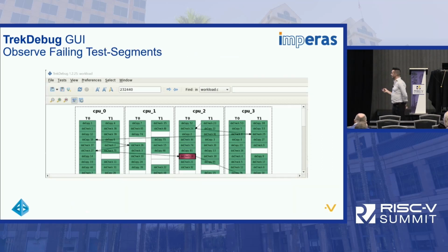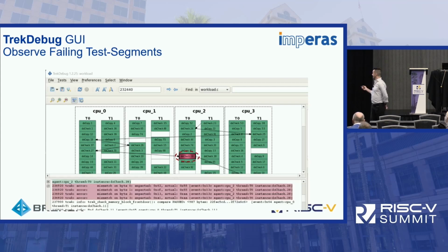What you actually have the capability of doing is taking a scenario and then see how that scenario is executed and where the context switches are, where you switch between different processors, between different cores from the beginning to end. And we think this is a very powerful tool, especially when you're getting errors, because you can see not just where the error happened, but you can also see what else was going on in the other cores and the other threads when the error occurred.